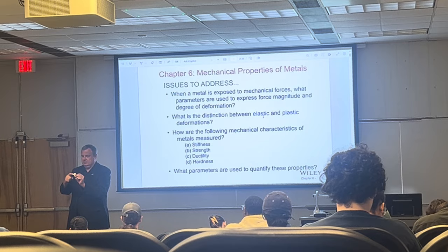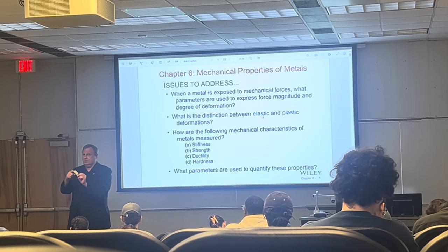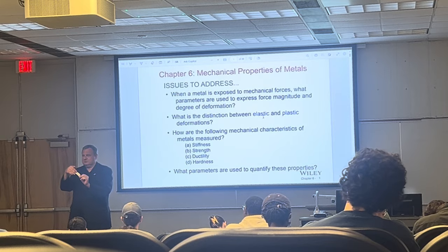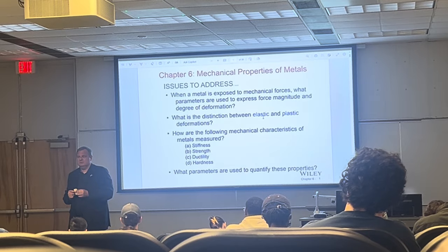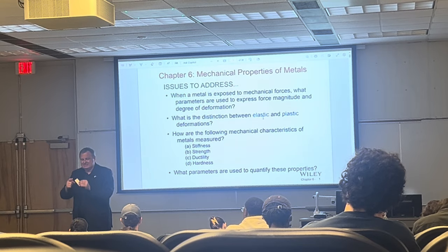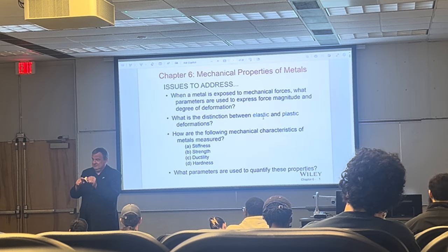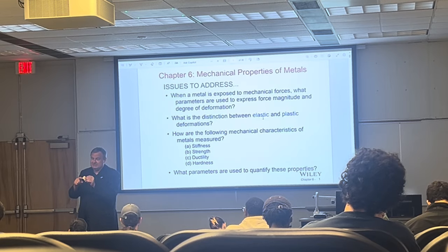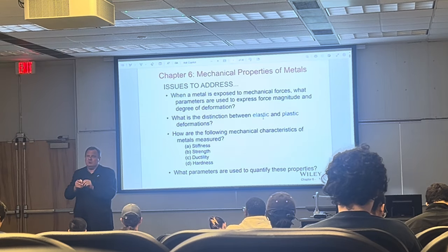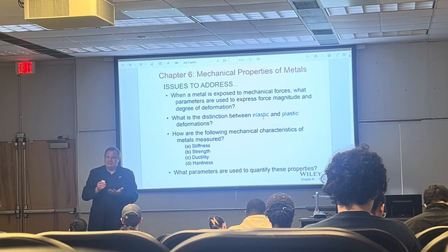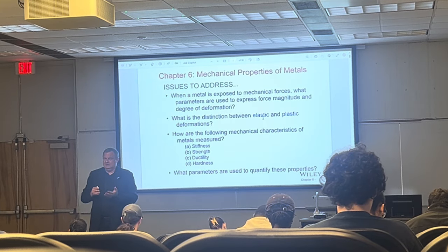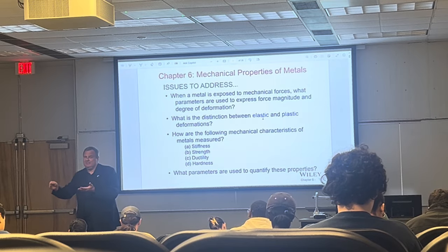Okay? But once I let go, what is the nature of this springing back? What kind? Plastic was during loading. Yes, unloading is elastic because plastic deformation happens by the motion of those planes of atoms. And those planes of atoms, once they move, they stay there.